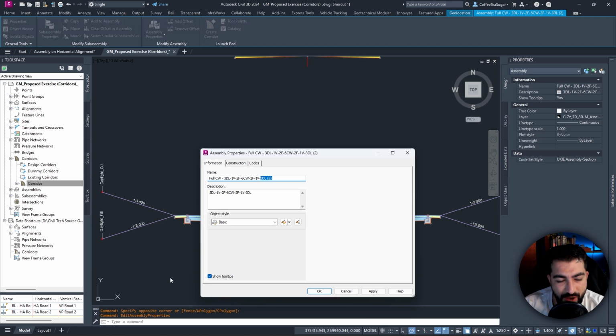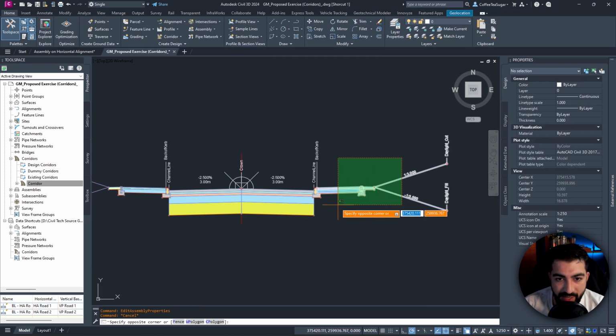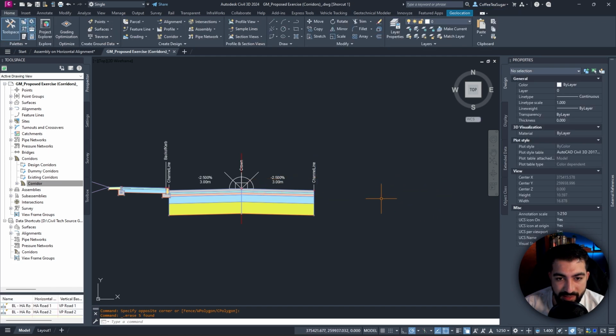So we're driving from south to north. So the right hand side will be absent. So we're going to remove the footpath, the verge, and the daylight. And I'm just going to call it not full carriageway, but just right hand side junction. Actually, I'll name it right hand side incoming junction. So basically what I'm telling the software is that on the right hand side, you'll be expecting a junction here.